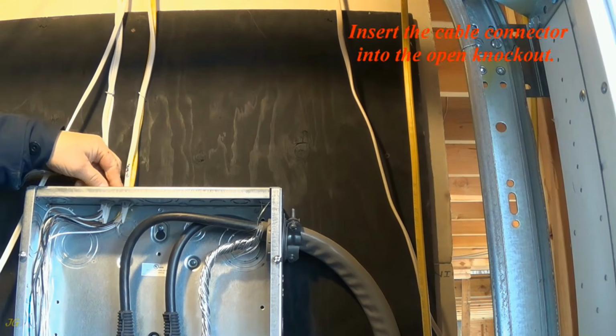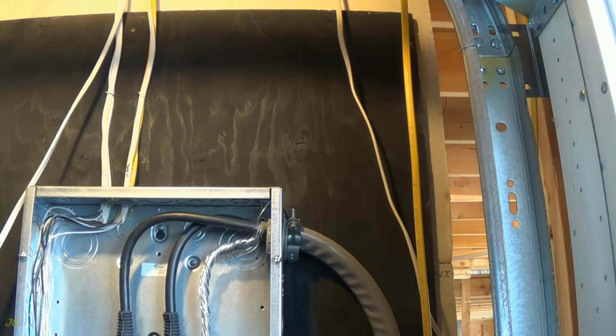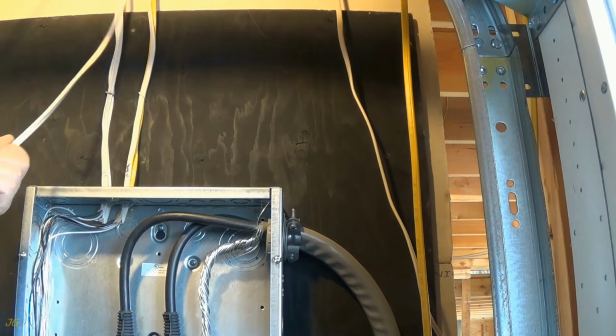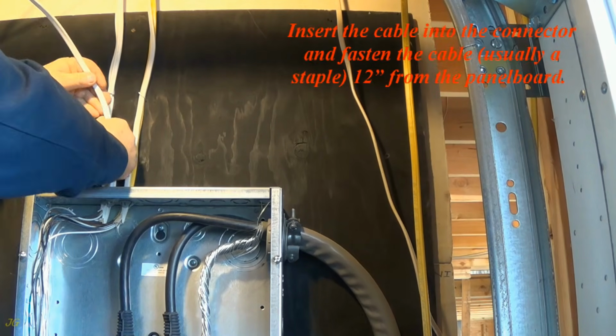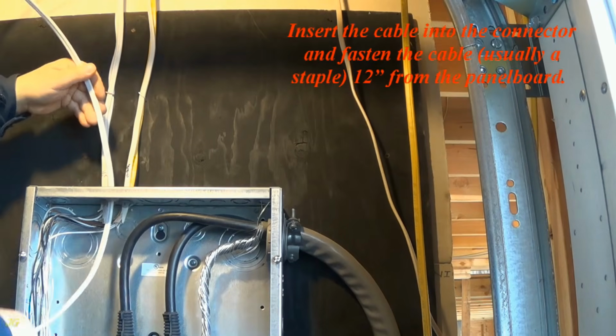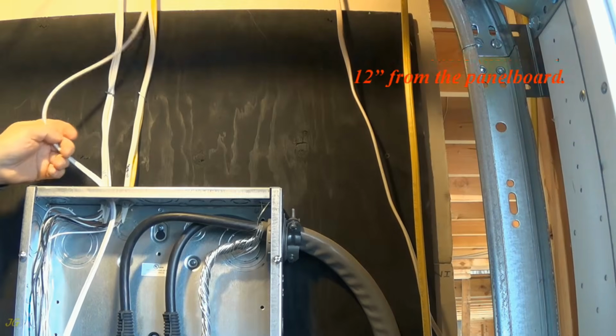Insert the cable connector into the open knockout. Insert the cable into the connector and fasten the cable, usually a staple, 12 inches from the panel board.